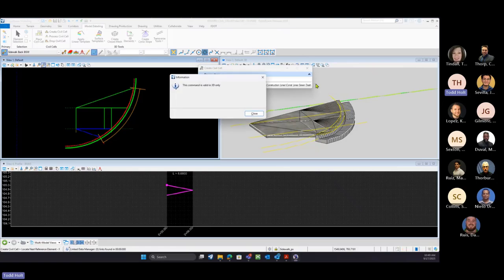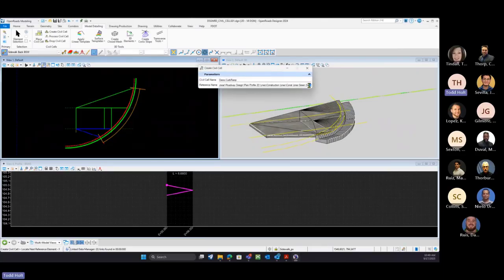And we'll set this is ref. And maybe this is our curb back top. That's going to be profiled. I just got click happy, so we're going to come in here and do a spec base, and this will be our ref. Here back top. And we'll say that's profiled as well. We're going to hit tab again. So anytime we name the reference, we're going to hit tab to lock that name in. Then we can go select the reference.